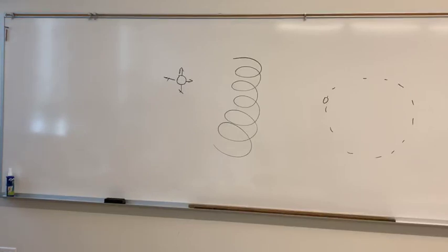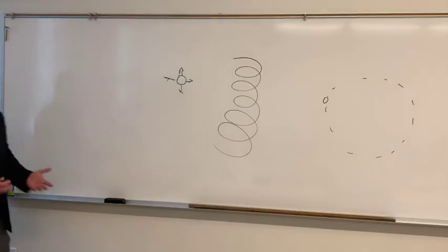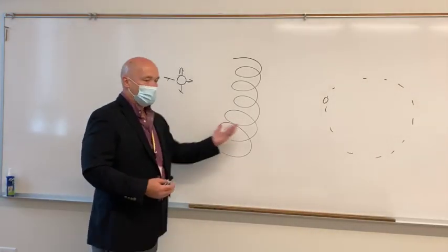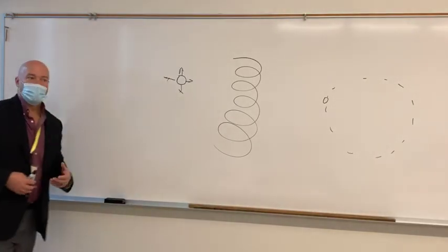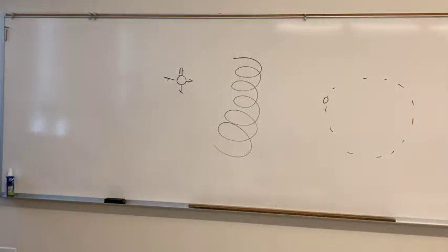The magnitude of the induced current depends on the strength of the magnetic field. So the stronger the magnet, the more electricity you can create. Then the velocity of the magnet as it moves past the conductor. So you had to have a changing magnetic field. The influence of the magnetic field had to change in relationship to the wire. So the faster you moved it, the more electricity you create. Then the angle of the conductor to the magnetic field, and finally the number of turns upon the conductor.